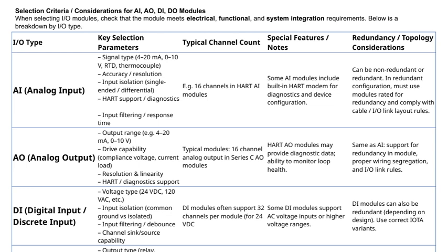Support for HART and diagnostics can provide valuable device health information. Additionally, input filtering and response time are important for signal stability and system responsiveness. Some modules include a built-in HART modem for easier diagnostics and configuration.